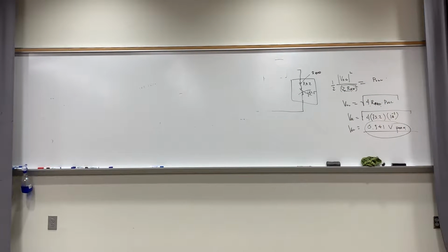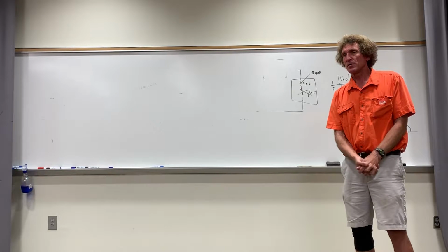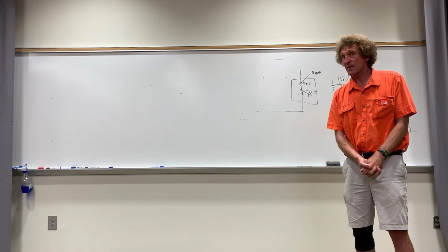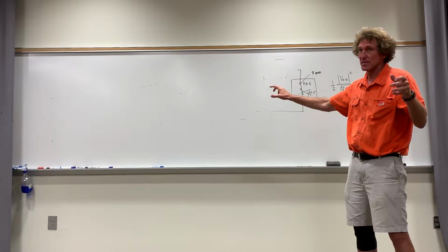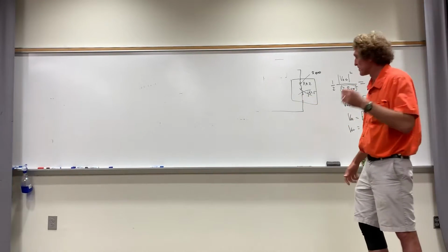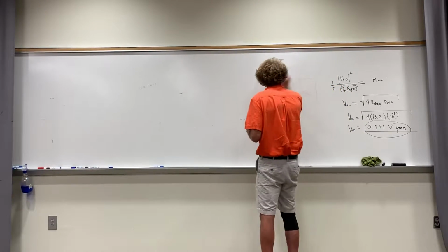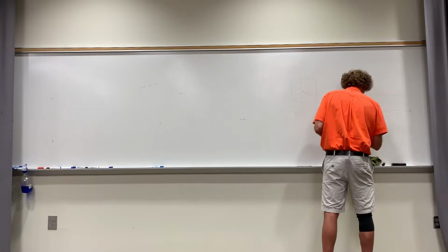Where are you looking? That same page, 43, equation 8.12. Because it was matched, wasn't it? No, 10 ohms was there. Remember, he put 10 ohms. That's the idea. He put a resistance that is not optimized for maximum power transfer. If it's optimized for maximum power transfer, exactly half the power received is dissipated in the load. The other half is re-radiated. There's a mistake. It's a factor of 2. Glad we did that one.